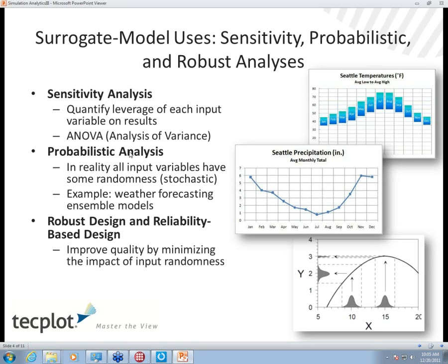This would be before you start a large production CFD parametric study. There's somebody who's going to sit down and say, is 10 million grid points enough, or do I need 100 million grid points to actually get an accurate solution? And so, in that case, you will probably run only 3 or 4 grid resolutions to make your decision. Right. The ability to compare those can be very helpful.